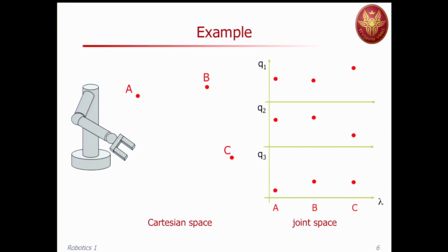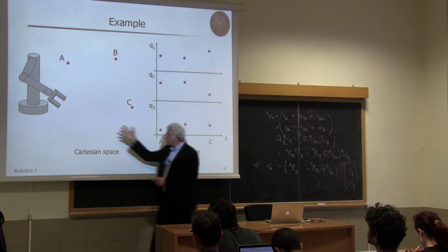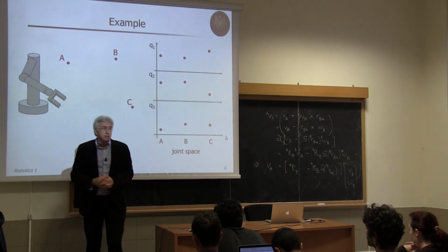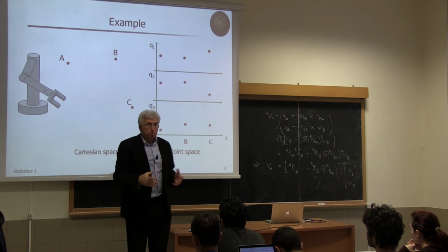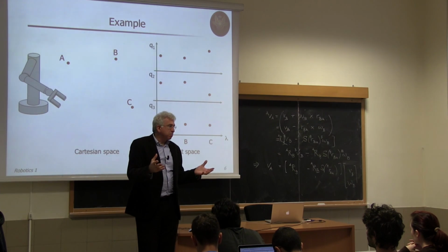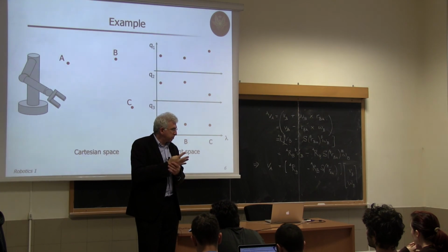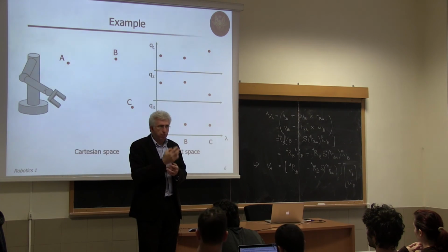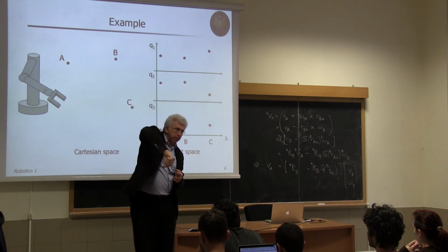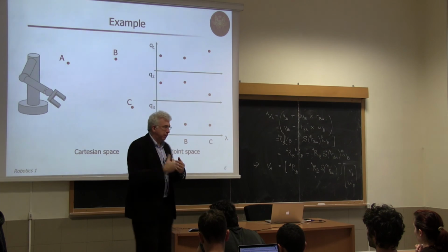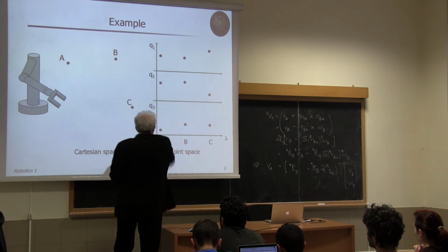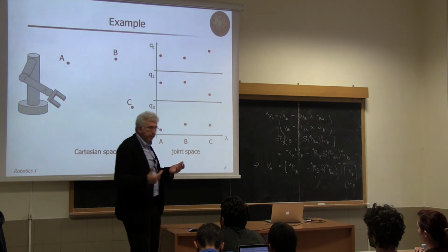Now, it makes sense here, if you have chosen for this robot, this may be an articulated 3R robot, it may have, in the regular case, 4 inverse kinematic solutions. Okay, because I would have elbow down, elbow up, and then front facing, or elbow down, back facing. Okay.